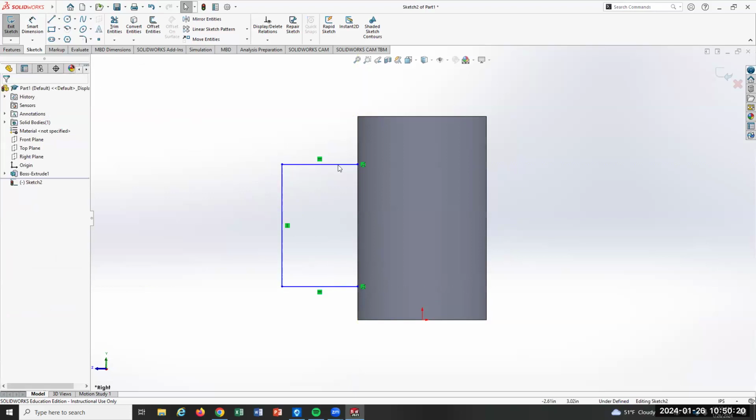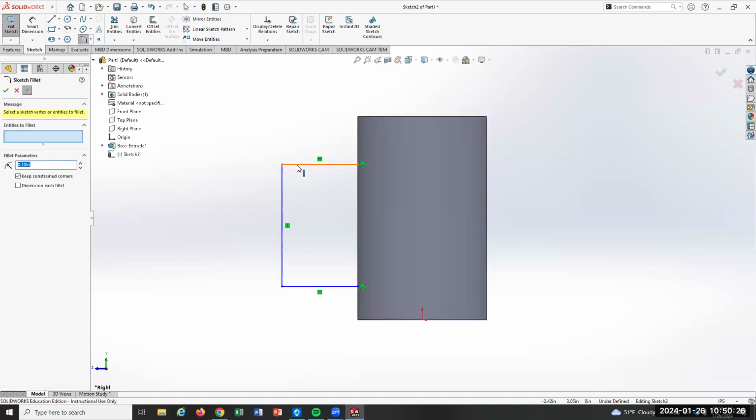But I could make it a series of arcs, but I also can do things like round corners, right? So I can go from here to here and make this rounded corner, and the adjustment's right here. So let's go 0.5. I like that. And then I can also keep clicking objects and it'll put them in. So this is just the display of what's going to happen, right? Here's the two fillets that are going to go in. Once everything works, this is in sketching, correct?